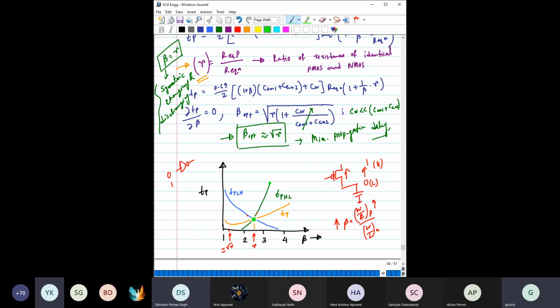Okay, so good design would be where the TPLH and TPHL are quite close, and for those designs, taking TP as the average value would make more sense compared to knowing the extreme values, because they are almost similar, right? Yes, exactly. This was my doubt. Like before, when we were going for minimum propagation delay, TPLH is significantly higher than TPHL, right? Yeah, okay, thank you.